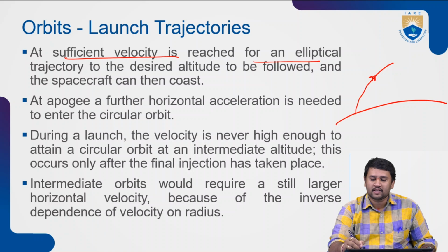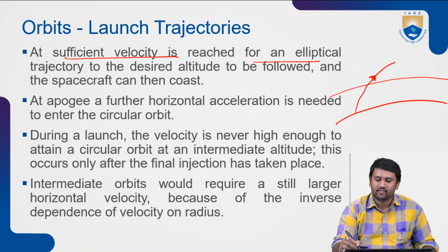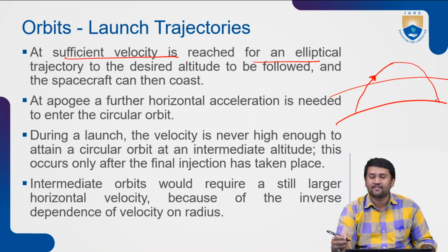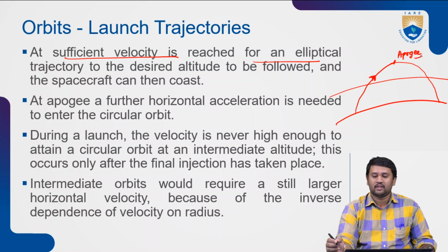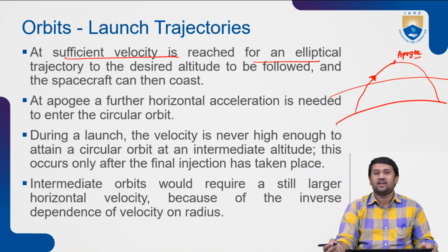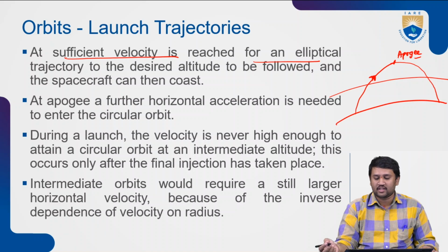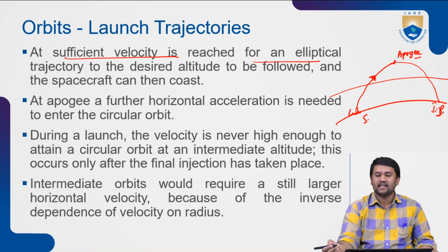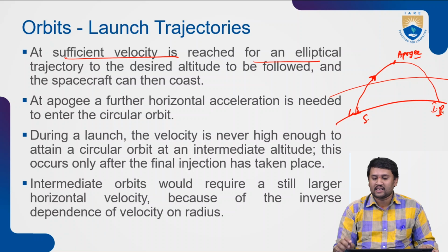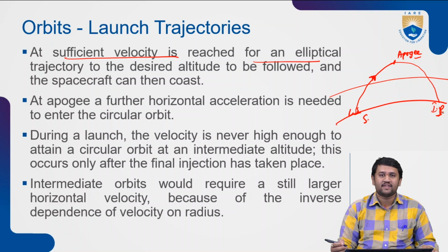Now, this is my rocket that is flying through the atmosphere, right? And this will be my path. If I am pushing out through, this will be my apogee, right? Now, in this case, we are not yet in orbit. We are in the progress of launch, right? And this is the Earth surface launch site, and this is the impact site. Why I am talking about impact is basically that the perigee doesn't exist till now, right? In order to have a clear perigee, you are supposed to be in a complete orbit, to say that my nearest point towards the Earth's surface is my perigee.